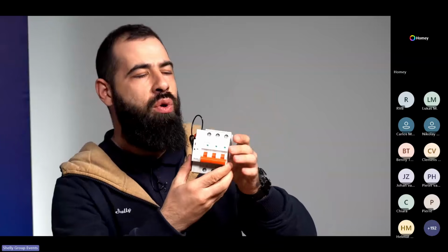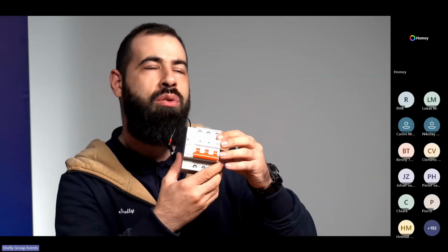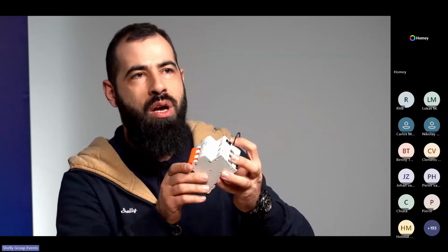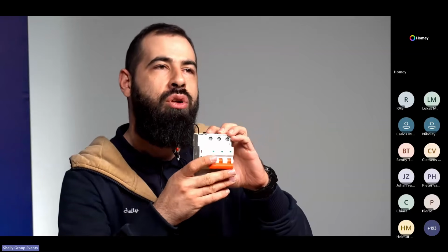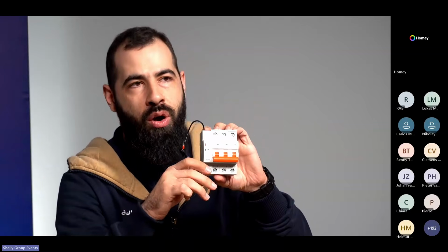As you may already know, it is powered from one side. It can be controlled either via Bluetooth or Wi-Fi. If you want to go a more professional way, you can always plug it into the Ethernet, and then the possibilities to control it expand, not only when a short circuit comes on the controlled side of the circuit, but of course you can also switch it off.